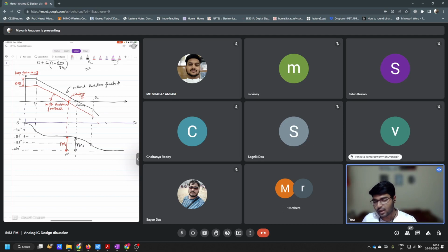So that is why when you design this Miller-compensated op-amp in industry, when you want to do something practical or useful with op amps, you always have to make sure that it doesn't become unstable. Let's say you want to make a product out of an op amp and sell it in the market. You do not know what the consumer will be using it for. They can use it for unity gain configuration, or for a high gain application. So it is a difficult task to make it stable across all possible cases. So an engineer has to design it for the worst possible case where the op amp can become unstable.